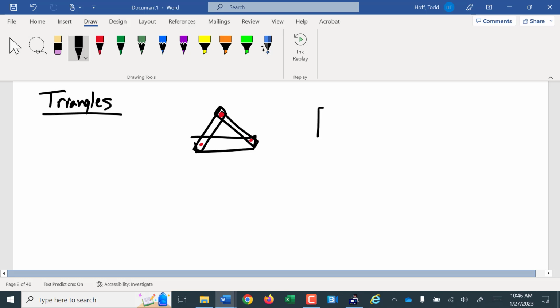Whereas if you had 4 pieces of material, if you just put pins through the corners to hold them together, if you push on it, that thing's going to push flat. It's a process we call racking, where it just bends over on itself. Racking means it goes out of a rectangular form into a parallelogram form.